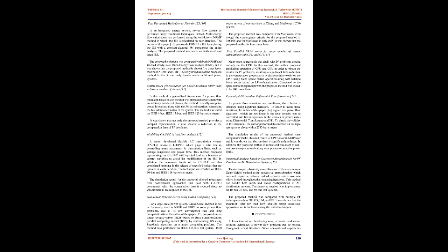Modeling UPFC in load flow analysis [12]. A recently developed flexible AC transmission system, FACTS, device is UPFC, which plays a vital role in controlling many parameters in transmission lines, such as voltage magnitude and power flow. This method proposed representing the UPFC with injected load as a function of control variables to avoid the modification of the Jacobian matrix. In addition, the maximum limits of the UPFC are also considered, resulting in the release of specified values that are updated in each iteration.